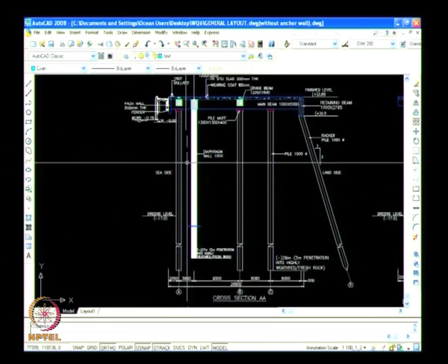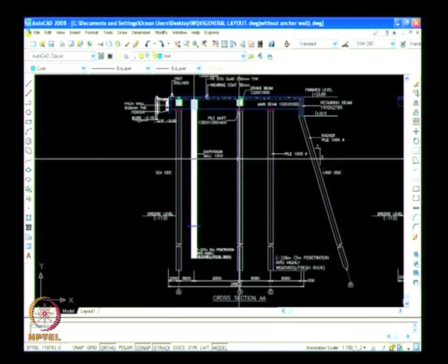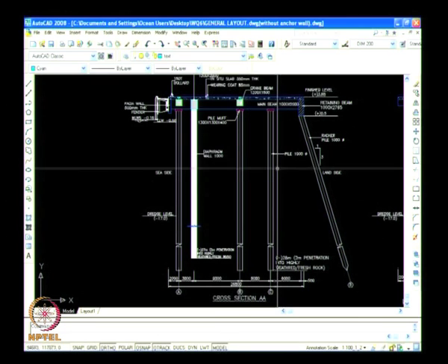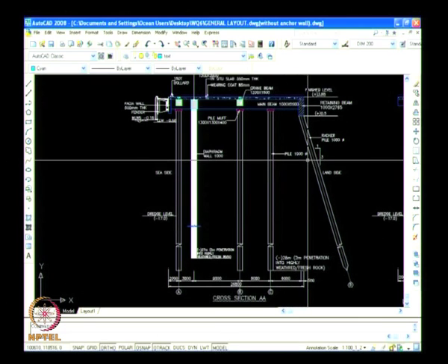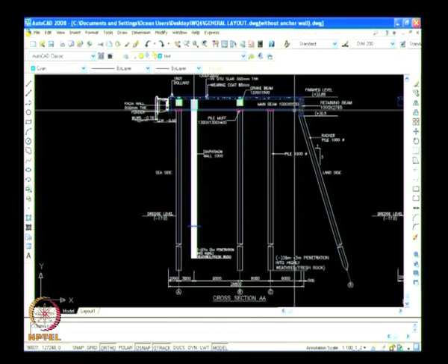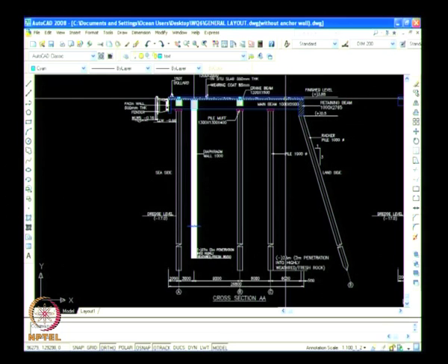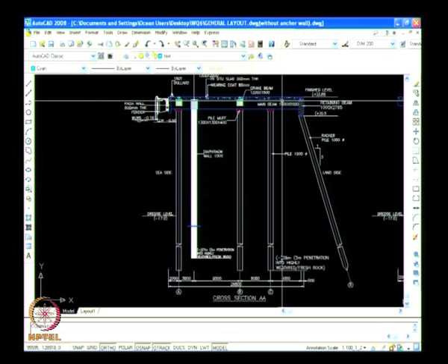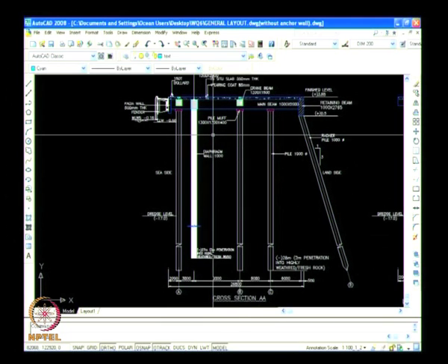Finite element discretization is a 2D analysis in which we take a typical 4 meter panel, we idealize the pile, beam, vertical pile, diaphragm wall and raker pile as beam elements, and the deck system also by beam elements. We do not model the slab which is connecting the beam, it is about 350 thick, and we apply the various forces acting on the structure and do the analysis.